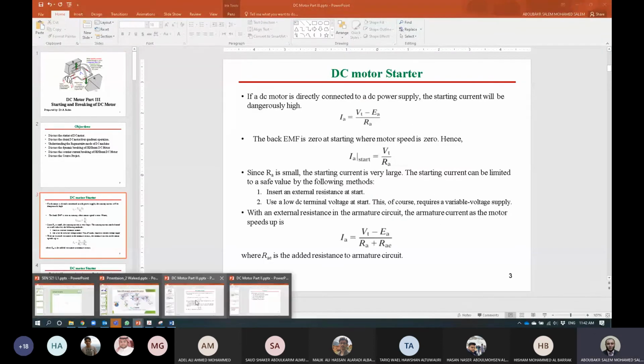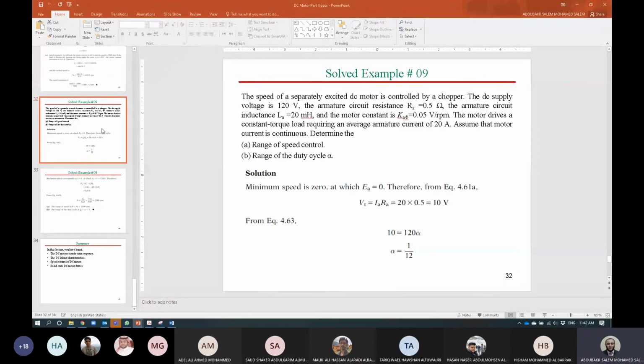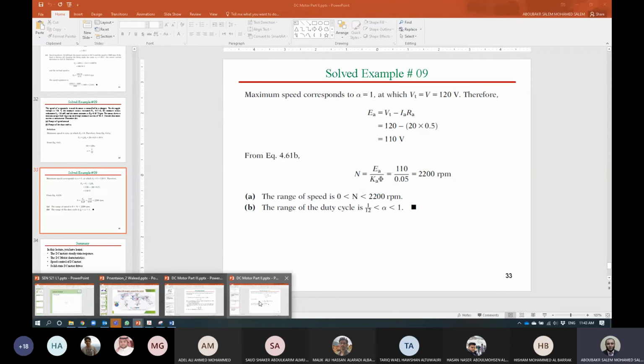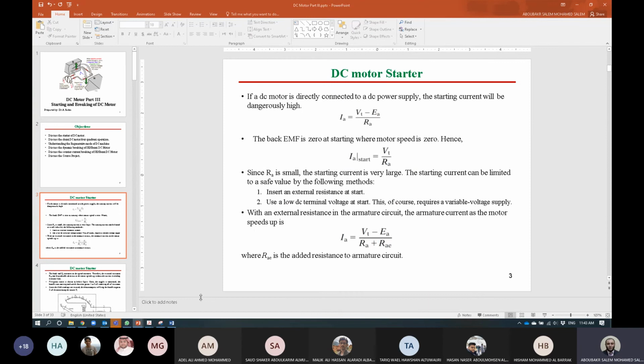We can see quickly. 0.05, 20, and the motor voltage was, let's say, at rated, here at maximum speed we obtained the motor voltage of 110. So assume 110 and 0.05 resistance for 20 amps. If we calculate it like that, 110 over 0.05, the current is 2200.